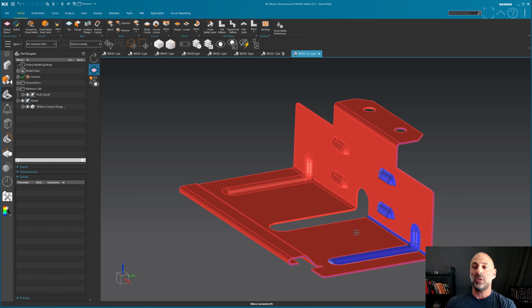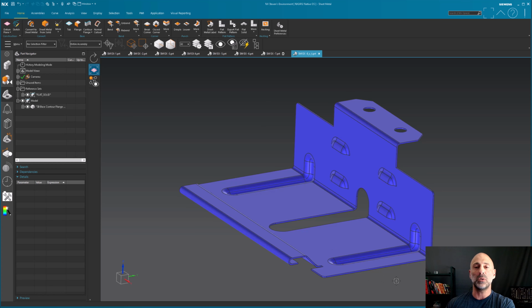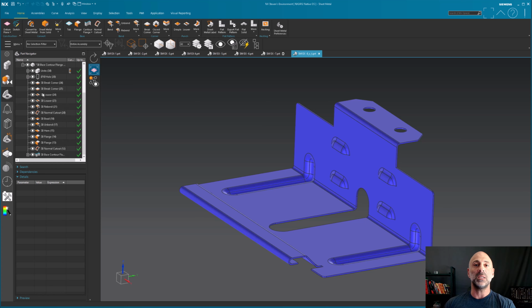So we take and redesign basically this bracket. You get a dummy solid, and then using various methods, again, swapping between creating things inside of the sheet metal application and then going into, like, there's my mirror geometry and holes and other things in the modeling application. So we talk about when to use what and swapping back and forth and proper application for that.